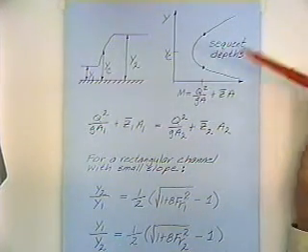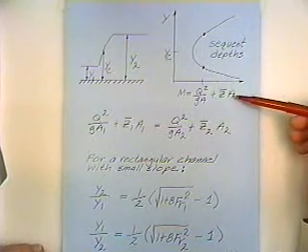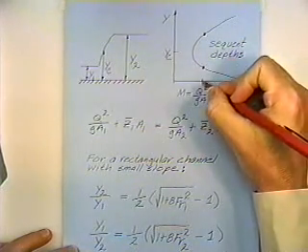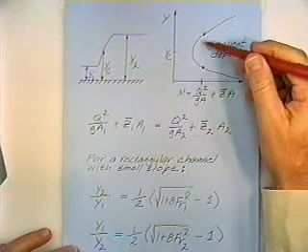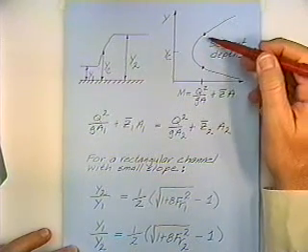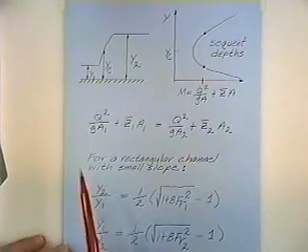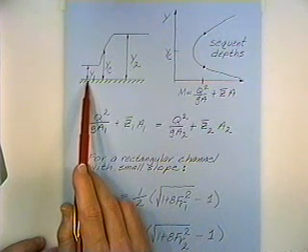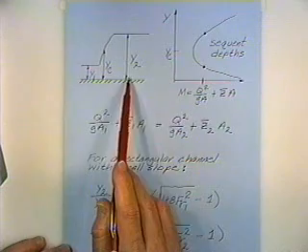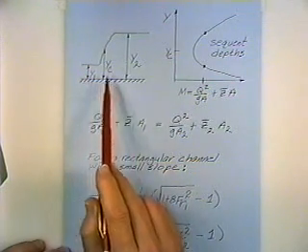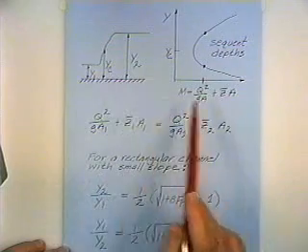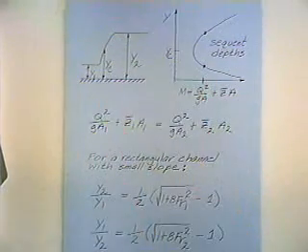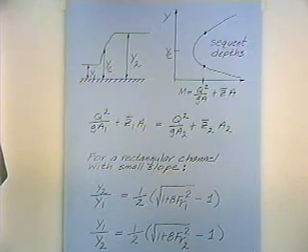Both conditions hold true. For a given specific momentum, I'm plotting depth versus specific momentum here. For a given specific momentum, there are two different depths that have that same momentum. We call those sequent depths. In a hydraulic jump, that would represent the depth before the jump and the depth after the jump. So we've got the same specific momentum before and after the jump, and the equation holds true in both places. Those are the two depths at which the same specific momentum holds true.